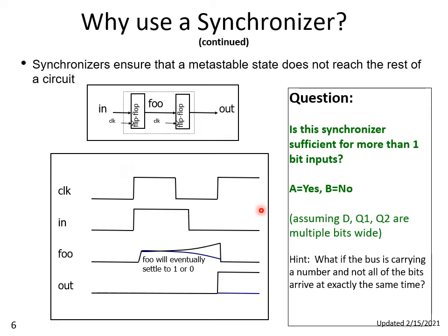then the value of the input would eventually make it to the output of the synchronizer, within a couple clock cycles at least. And the fact that the first flip-flop is metastable and settles out randomly doesn't necessarily hurt anything, because the only consequence of that metastability, if in is held long enough, is that it just causes a variation in the amount of time it takes for the input change to appear at the output of the synchronizer.